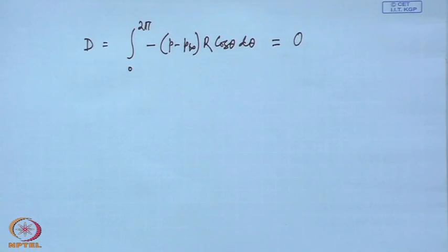That is the failure of classical theory, that no matter whatever you do, a two dimensional ideal flow will give 0 drag. And one needs to think that perhaps two dimensional ideal flow assumptions are not adequate. We have come here through some assumptions, no? We have assumed that the flow is incompressible, inviscid, irrotational. Obviously, there is some flaw somewhere in those assumptions.